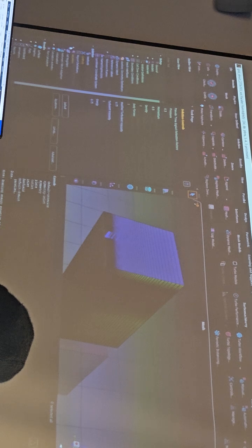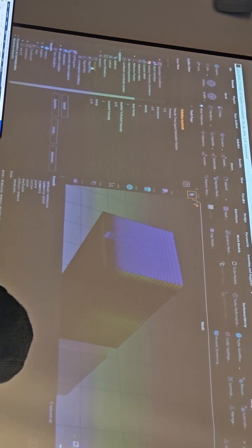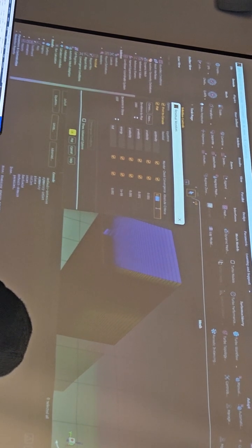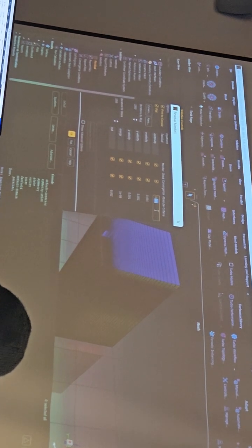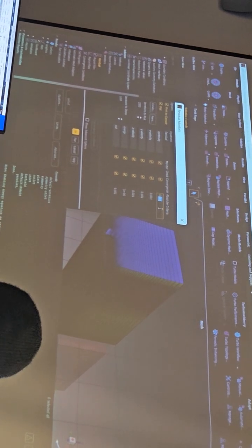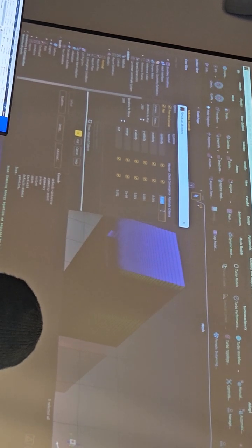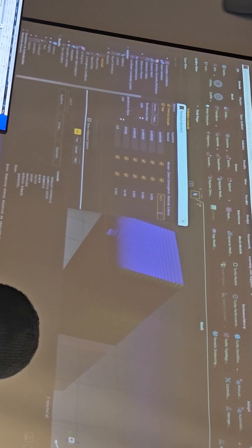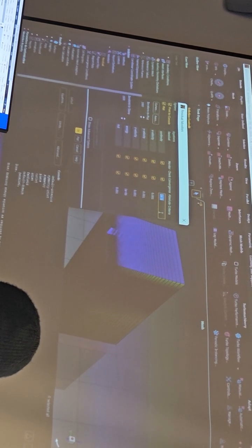And then in monitors, if you expand monitors, here you have residual. If you double click, here you can set the criteria that you want to set for having a convergent solution. So how low the residuals have to be. Last week we set them to 10 to the power of -5, and I'm doing the same for all of them.